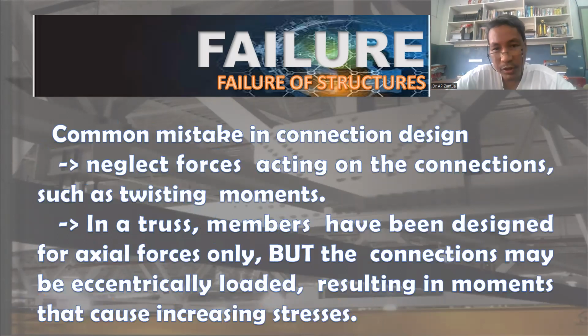So common mistake in connection design. We neglect forces acting on the connection itself, such as the most common one is twisting, because we usually consider what? Axial forces, but sometimes we miss out on moments or twisting moments.